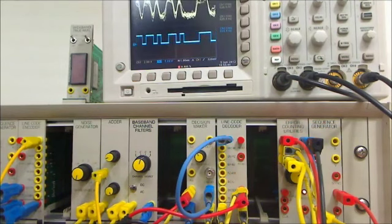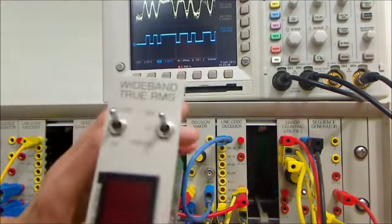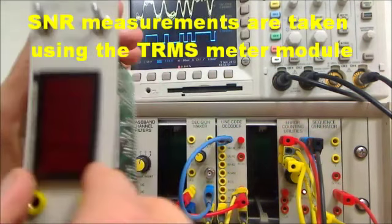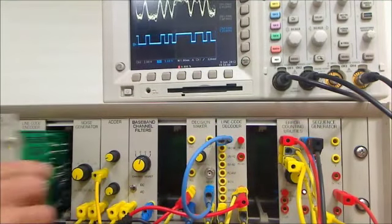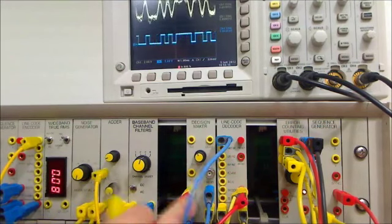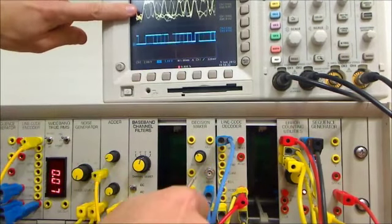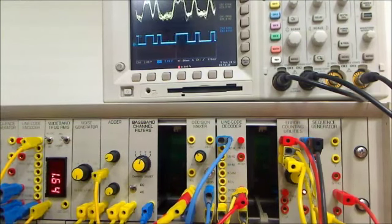Now, one thing we haven't looked at at this point is how do we actually measure signal to noise levels. That's simple enough. We take this module, it's a wideband true RMS meter, which has an 8-digit true RMS meter and a 3.5-digit display. It's actually a very accurate module. Plug it in, take a lead. Let's take a look at the signal at the decision maker, which is up here on screen. Take the lead, input that signal into the true RMS meter. So now you can see a reading.